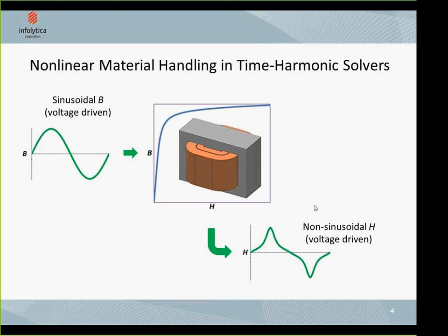a magnetizing current. And this case is more applicable because we expect transformers to behave in a similar way. So when you are doing the iron losses, you are going to connect either the secondary or the voltage, depending on the supply that you have, to a sinusoidal driven source. And then the corresponding H field will be the magnetizing current.